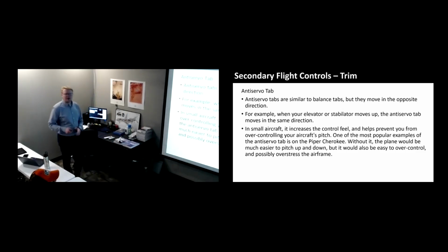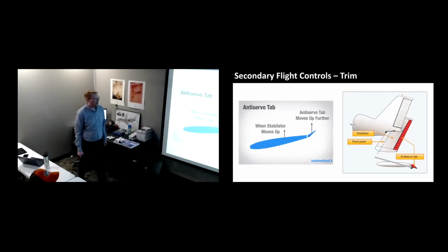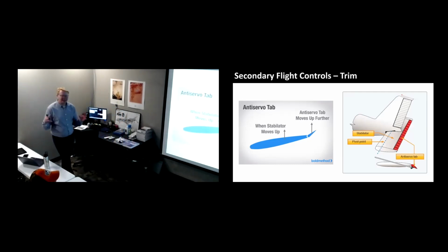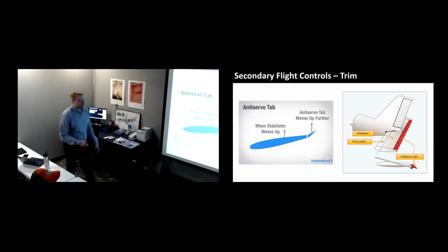Now, when you move the wheel in the cockpit, it does physically move that piece and it limits the range it moves in. Different design. Piper is the one who selected this one in their design. Nothing wrong or right with it. It does the same thing, except it moves in coordination with the entire surface. Only reason they did this is since the entire stabilator is moving at once, they needed to move it in coordination with its angle of attack change as a whole. So this moves in coordination with this. It does the same structure though, same piece.